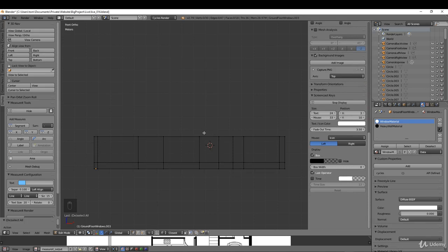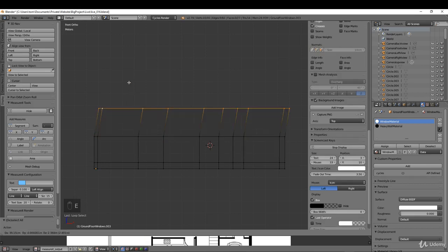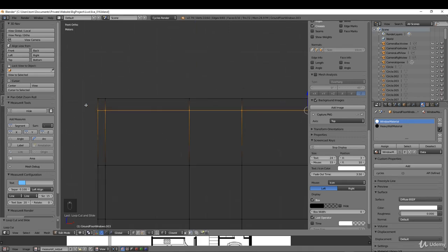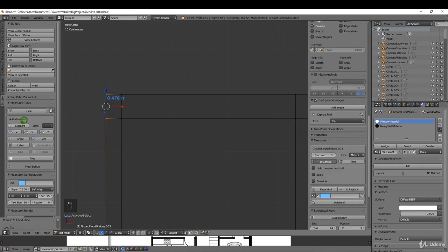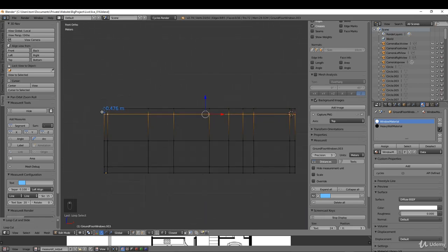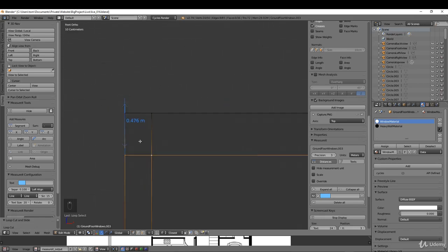What I'd like to do is extrude this up again to the actual ceiling height. So I'm going to alt select this entire edge here, press E, press Z to restrict it, and press 2.7. Okay, and that is the full height including the roof. So what I might do is press Ctrl R and just insert an edge loop. And for this, I'm going to zoom in over here. I want this to be 300, so I'm going to get a segment. I can alt select this entire edge. I can just zoom out to make sure it's selected.